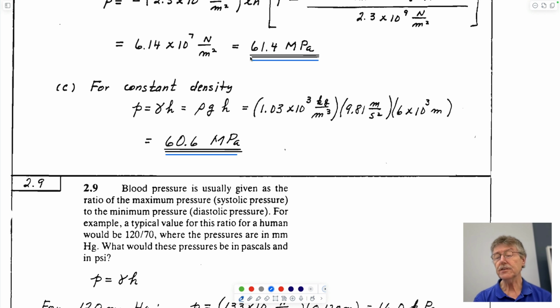And it's larger pressure if it's slightly compressible because, of course, when you apply pressure and you make the volume smaller, then you have to fill up the area to make it up to a cubic meter by some extra fluid, and that has extra mass, and therefore it has higher density. And so a column with a higher density as you go down is going to sum up to a larger amount. So it's just based on the idea that we talked about before.